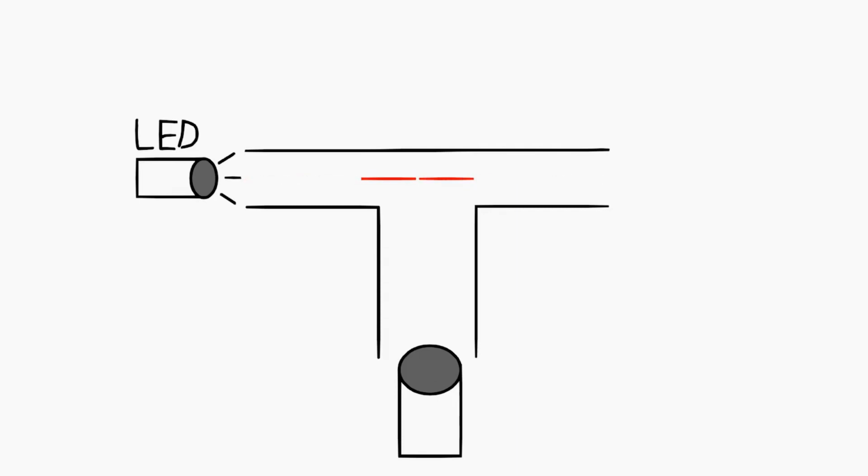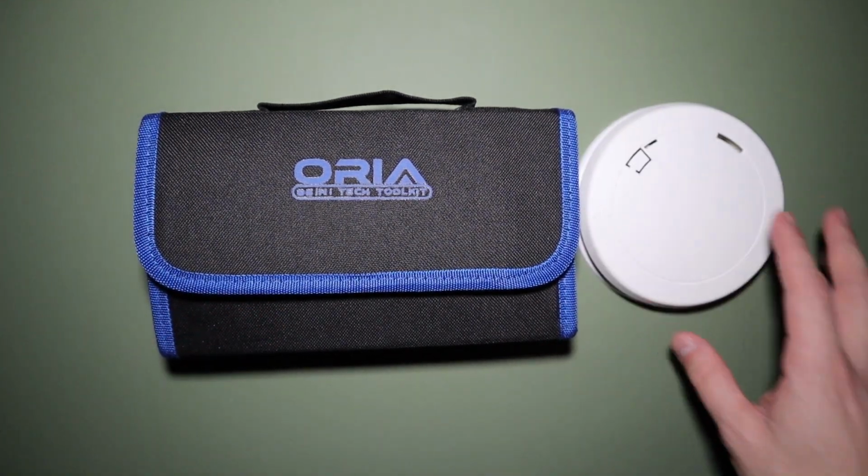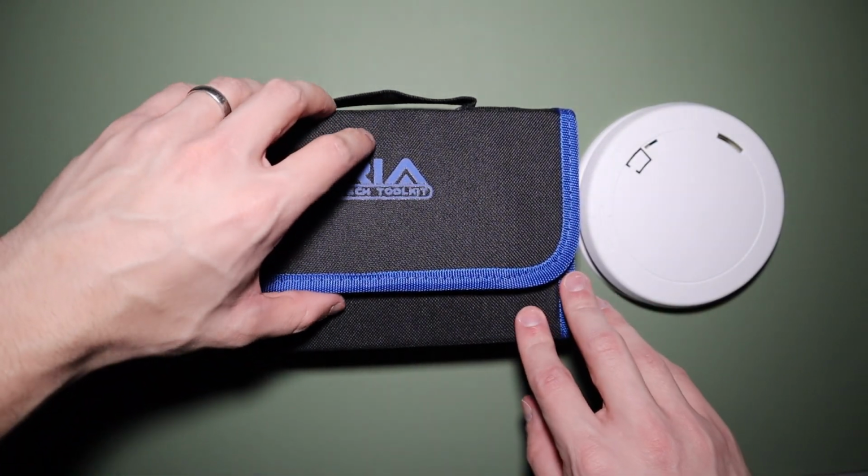A photocell, positioned at the bottom of the vertical base of the chamber, generates a current when it is exposed to light. Under smoke-free conditions, the light beam crosses the top of the chamber uninterrupted, not striking the photocell. When smoke is present, the light is scattered by smoke particles, and some of the light is directed down the vertical part, which strikes the photocell, triggering a current setting off the alarm. With the fundamentals of how smoke detectors work, let's begin reversing and learn how this is achieved in the First Alert smoke alarm.